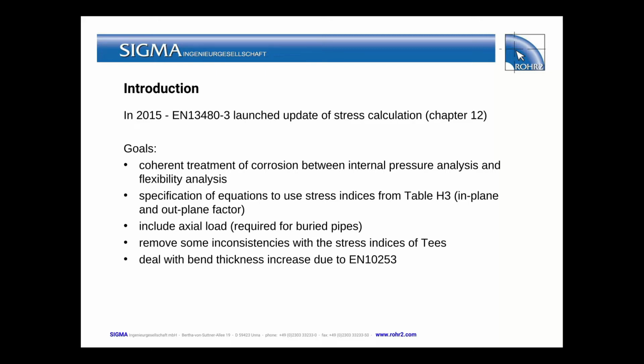This was especially required for the buried pipes in view of part 6 of the same norm. Also, some inconsistencies for the stress indices of T's were removed, and the increased bend thickness due to EN 10253 was also taken into account.